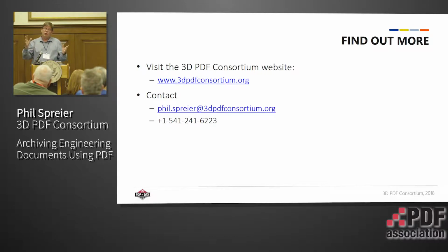I typically have that. So the question was, can you connect parts of what I call the flat PDF to the 3D PDF? So if I have, perhaps on the same page as my 3D scene, a table with a bill of materials, can I click on something in the bill of materials and have it do something to that 3D model? Yeah, absolutely, you can do that. The JavaScript allows the flat parts of the PDF to interact very well with the 3D parts of the PDF. It's all very possible with that.